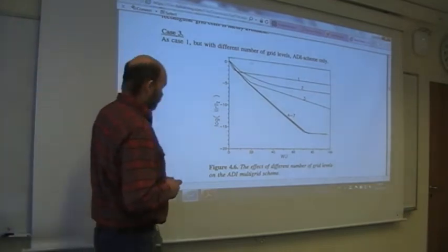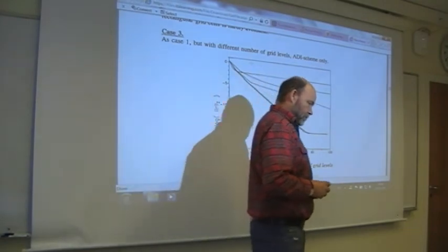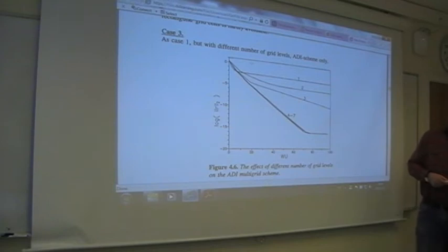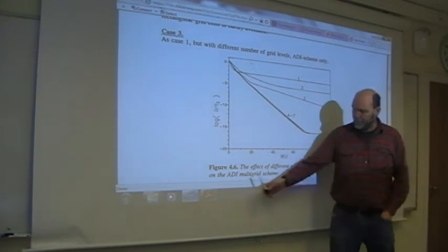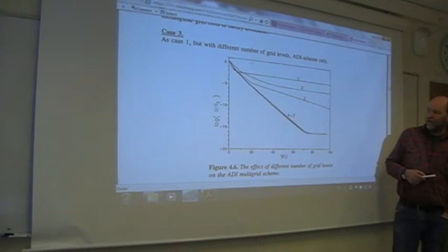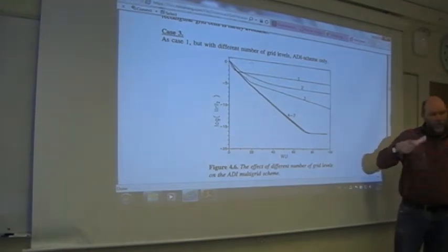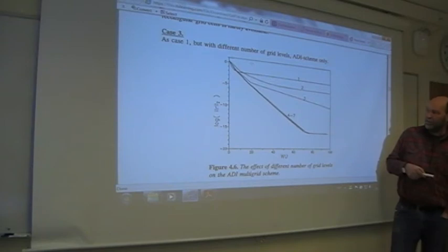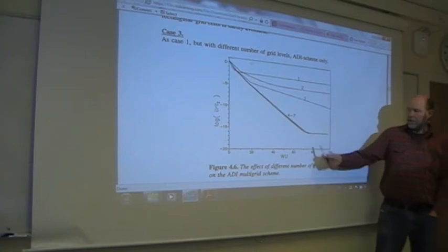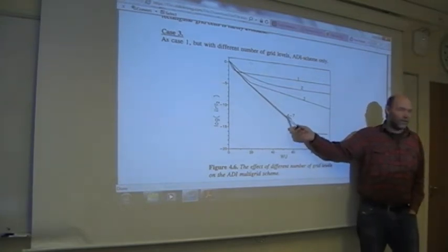So here, same as the first case, you had 7 possible grid levels. So now I used the ADI smoother, and just to play around to see the efficiency depending on the number of meshes you use. So here the efficiency just on the fine mesh, just one coarse mesh, 2, 3, and so on. And here 4 to 7, really no change.